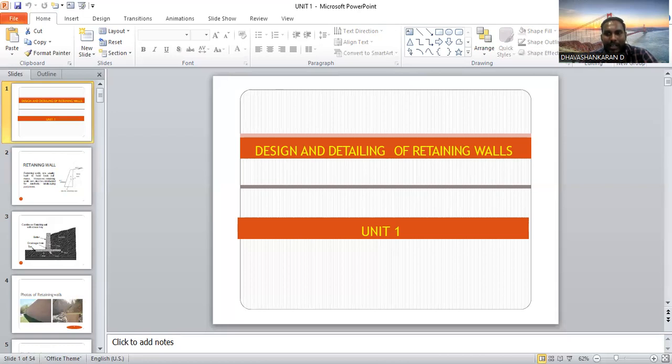In a cantilever retaining wall, we go for a shear key. While we are going with the shear key, it can resist all kinds of failure that act on a retaining wall. So there must be some conditions and criteria given for the design of the shear key. So this is the maximum pressure, and basically the triangle has been listed for finding the pressure distribution on the passive side and active side.